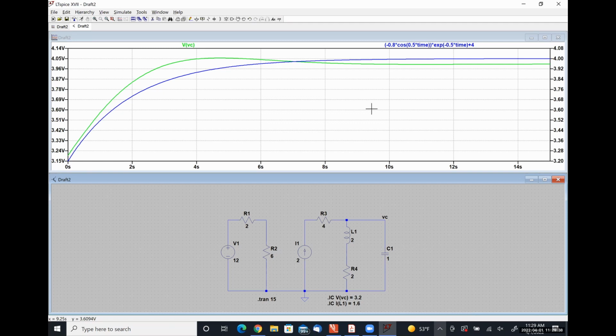I was trying to compare these graphs. Now, obviously, they're not of the same shape. So that's definitely a problem. That is indicative of problem 1, so let's address that first. 0.5 is the radians per second. It's the angular frequency. LTspice does everything in degrees, so we need to include a conversion factor here, only for our omega d term.